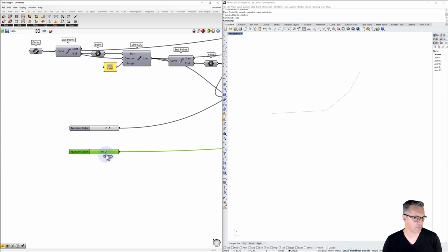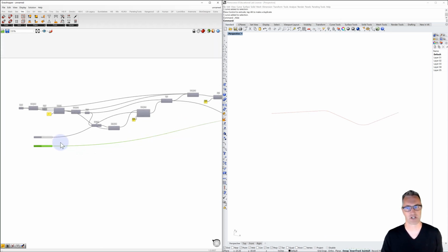And the reason why I'm constraining my slider to 120 is that any greater than 120, it seemed to change the size of the radius of the fillet and seemed to make it smaller. And I didn't like that. So now at least the slider gives me the kind of 120, or it gives me, by constraining, that option to kind of hold that. So that's working. And so this is nice.